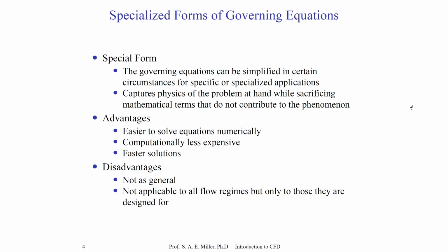It'll take time to understand this. This will give you an overview of probably the most popular and famous sets of equations which have been used in CFD through today. Do not dismiss the older solvers, especially in systems engineering settings where you need to generate thousands, if not tens of thousands, of CFD solutions to design a vehicle. That may come in handy, where today the full high-fidelity solvers like large eddy simulation or direct numerical simulation, or even a detached eddy simulation and unsteady RANS, which we'll talk about later in the turbulence modeling section, won't be used in a design setting for systems level design. And that's where a lot of engineers go today.